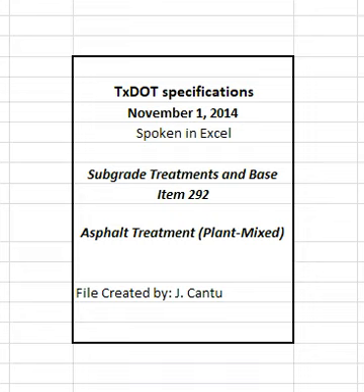2.1 Aggregate. Furnish aggregates that conform to the requirements shown in Table 1 and specified in this section unless otherwise shown on the plans. Each source must meet the requirements of Table 1. Stockpile aggregates for each source and type separately. Do not add material to an approved stockpile unless approved by the engineer. The engineer may allow testing of the proposed combined aggregates, rather than each source, to meet Table 1 requirements.